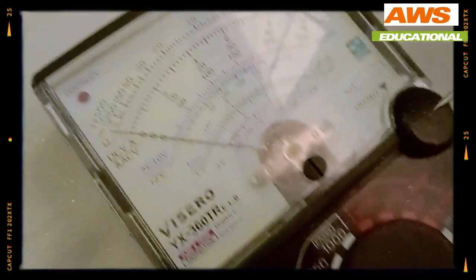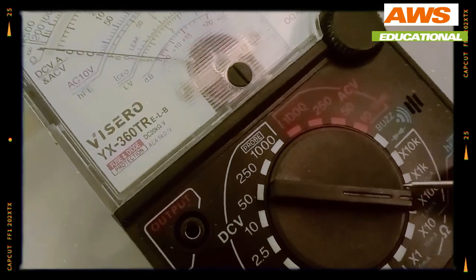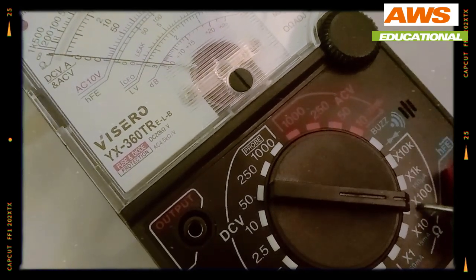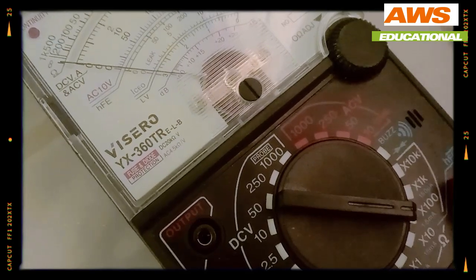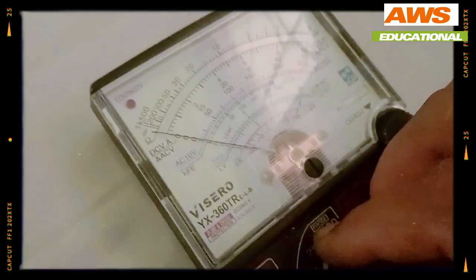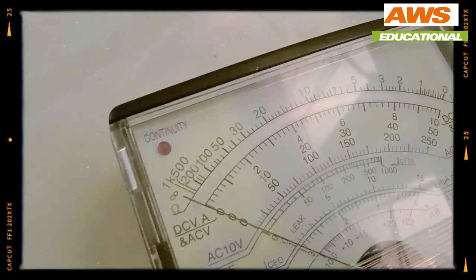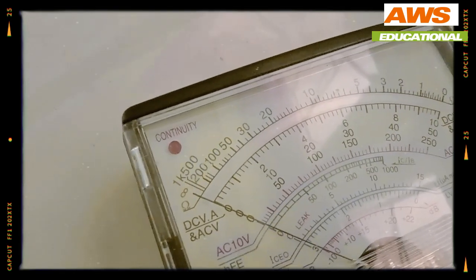3. Once the measurement is completed, it is a wise precaution to place the probes into the voltage measurement sockets and set the range to maximum voltage. In this way, if the meter is accidentally connected across a high voltage point, there is little chance of damage to the multimeter. Advantages of analog multimeter.